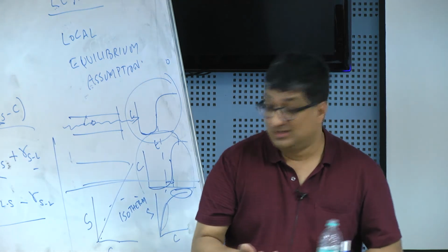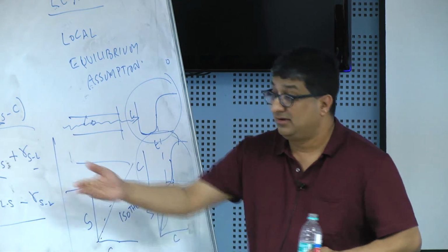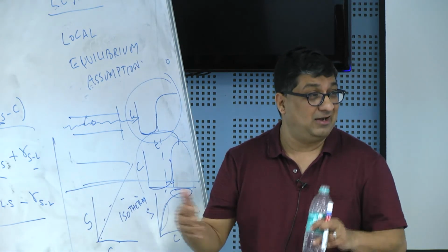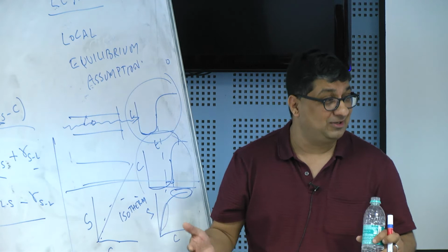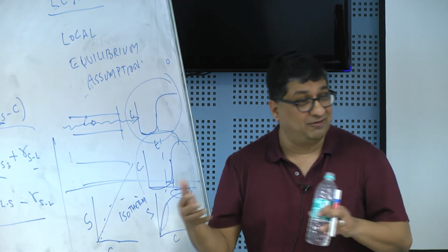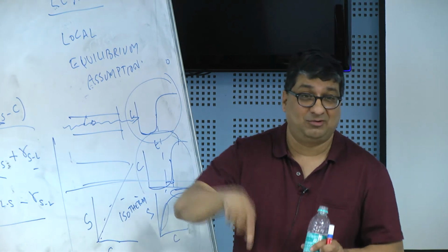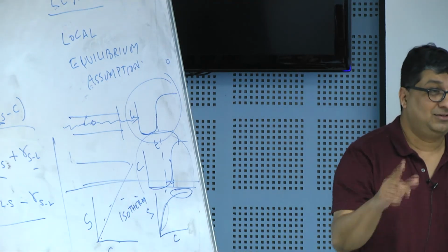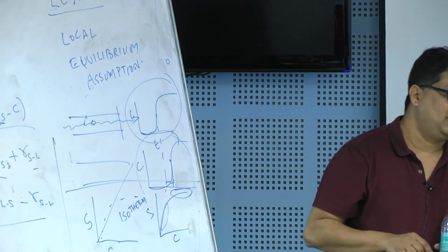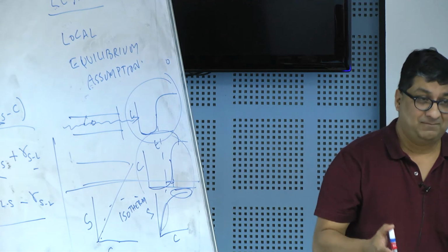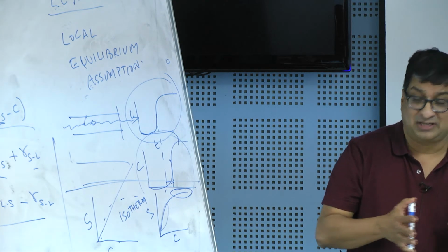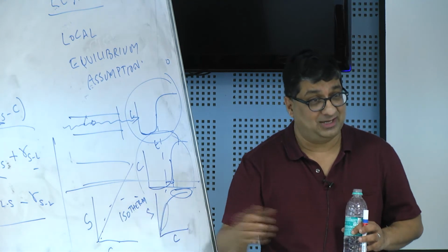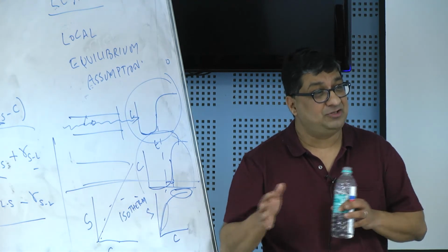Of course, if you use a linear isotherm, you will have a linear differential equation. Remember, we had a linear differential equation. If you have a linear isotherm, you'll maintain that linearity. If you have a nonlinear isotherm, you will turn the partial differential equation into a nonlinear equation, and again that equation becomes stiff. So even small changes to your Freundlich isotherm, like the Freundlich exponent, can change your breakthrough curves quite a bit.